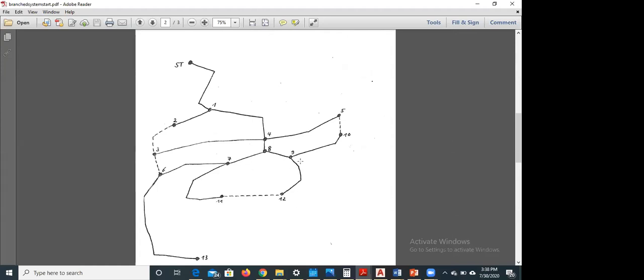Okay, let me talk about the 4 parameters. For the pipe parameters, the length of the pipe will be given to you. If it's not given to you, you read it off from the diagram. You read it off from your chart or from your AutoCAD file. Or your surveyor, once your surveyor takes the spot height, all you need to do is to use AutoCAD and connect the points. And then you can use inquiry tool in AutoCAD or your measuring tool, and then you read off the length of the pipe.